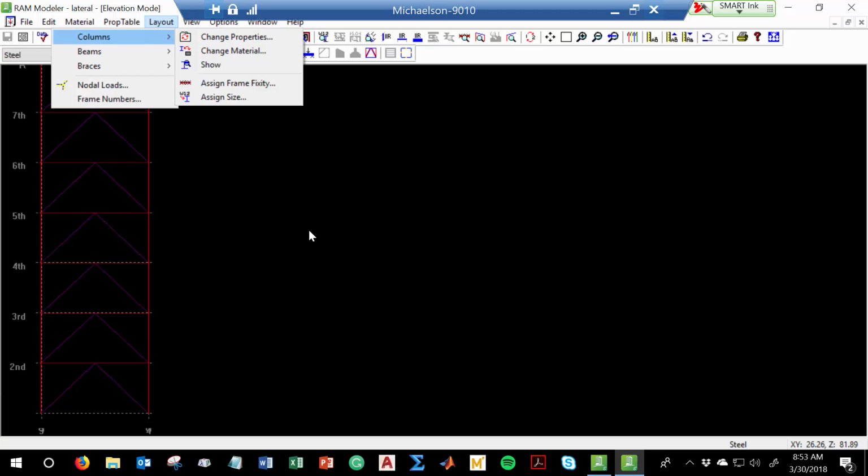Yes. Put one here, one here. It does that. That's 2 walls. But what if you have one diagonal wall? So you're going to add a whole other wall to the building? Instead of having 2 separate walls to resist diagonal loading, what if you just had one diagonal wall so it's less construction? Well, what about the load going this way?